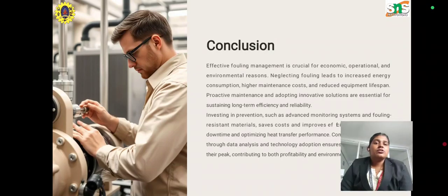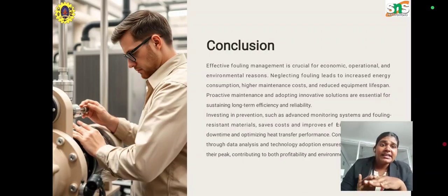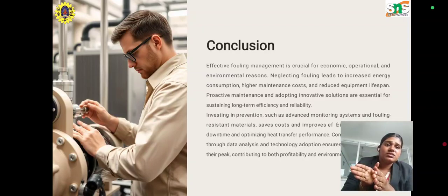So in conclusion, effective fouling management is crucial for economic, operational and environmental reasons. Neglecting fouling leads to increased energy consumption, higher maintenance cost and reduced equipment lifespan. So fouling and scaling can cause a major loss to the company and also in power consumption. So this should be avoided, and it should also be tracked regularly.